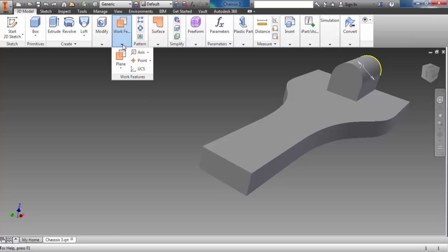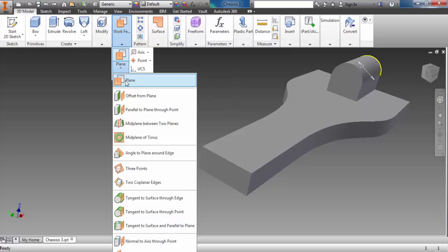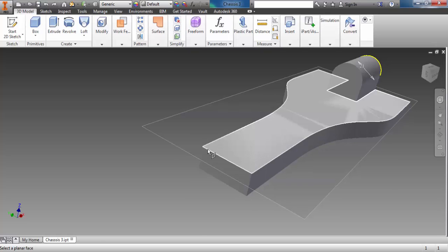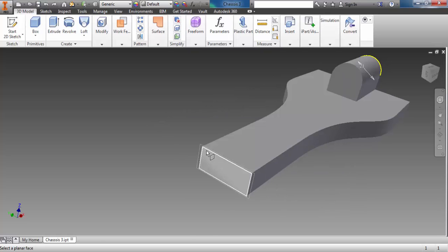So to find the work planes menu, click on that one. Click on plane, and we'll go to offset plane, and we're now going to say, right, this is the plane that we want the work plane to be parallel to. So we click on that, and because we wanted to move it further back, we type in -1 and click tick OK. So that is this yellow surface around there. That's the surface we're going to actually be drawing on, not the actual front part.